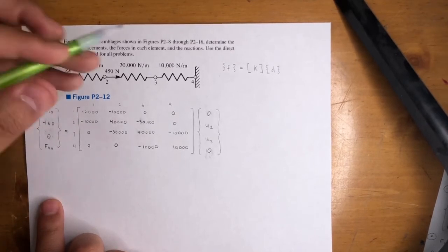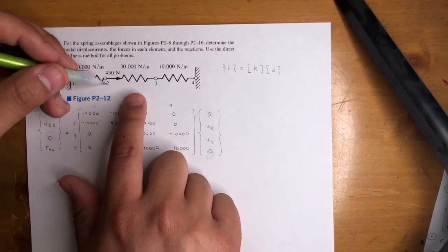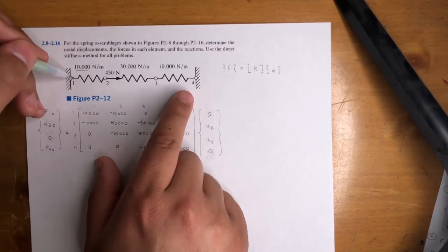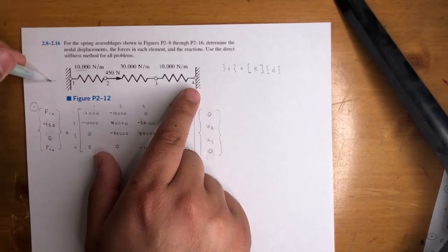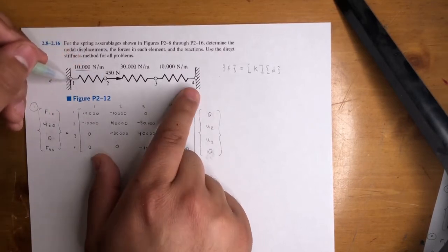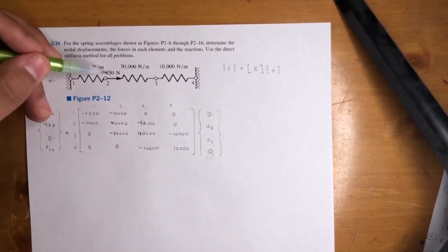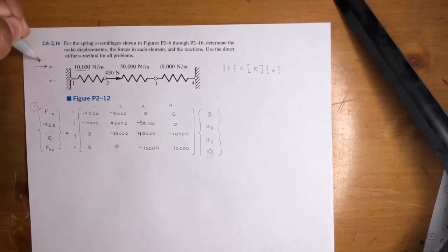There's a force at 1 and then there's a force at 2. Now, if you have 450 going to the right and nothing acting here, that means these two forces have to total 450 to the left. Now, it doesn't necessarily mean they're equal. It's not necessarily 225 and 225. It just means it has to be equal and opposite to this, right? Equilibrium, sum of the forces in the x. And this is our positive x direction.